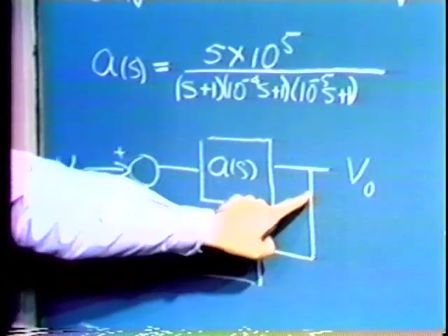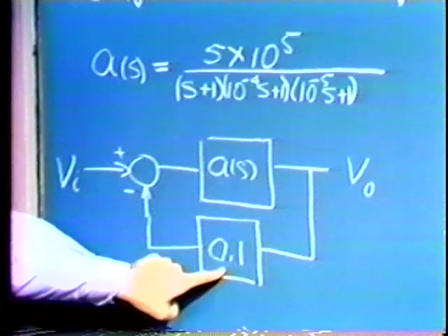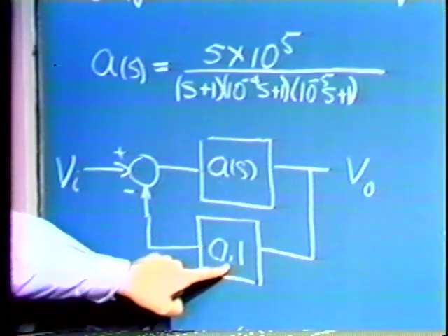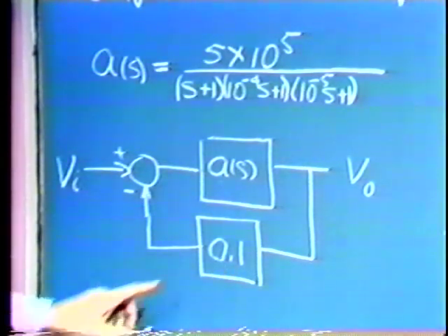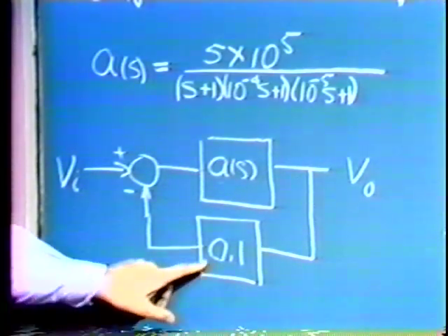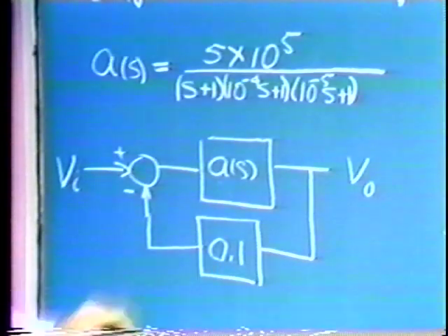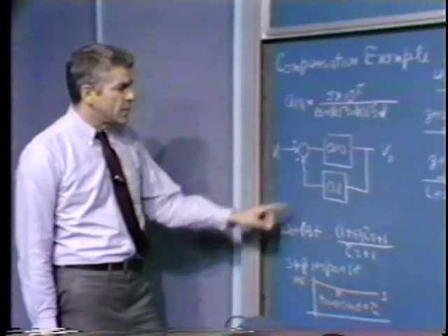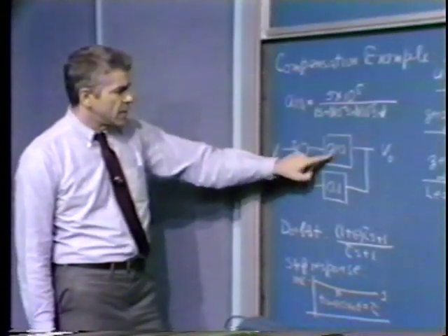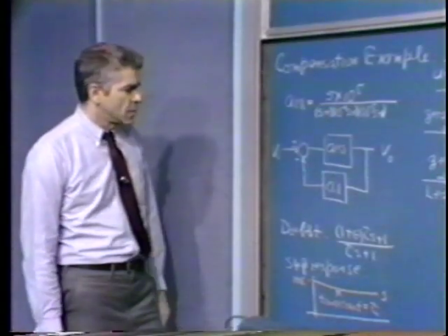And then in this particular system, we have a feedback transfer function F equal to 1/10, representing the attenuation associated with the 9R versus R valued resistor. This assumes, of course, that the feedback network doesn't load the output of the operational amplifier, and similarly that the input of the operational amplifier does not cause any loading on the feedback network. So under those sorts of ideal conditions, this is the block diagram that results. We, of course, substitute for A of S the expression above.